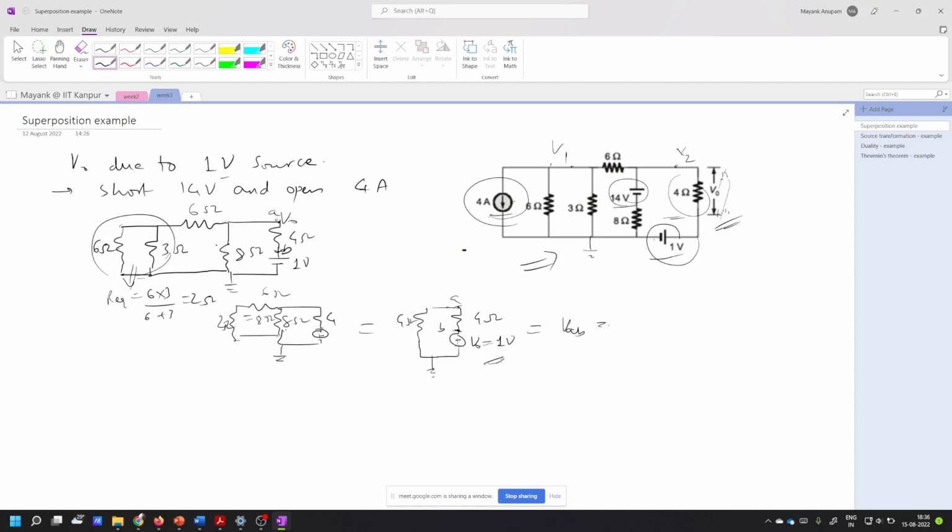Okay. So now tell me, what is this VAB in this case? Hello. 1/2, sir, 1/2. Equivalent resistance, right. Equivalent resistance is what? 8 ohm, right. You're correct, it is 1/2. But I'm asking about the voltage VA minus VB. 4 series, yeah, you are true, it is 1/2 volt. True. But you are telling the magnitude; I'm also asking the sign. So it is not 1/2, it is minus 1/2. Right.